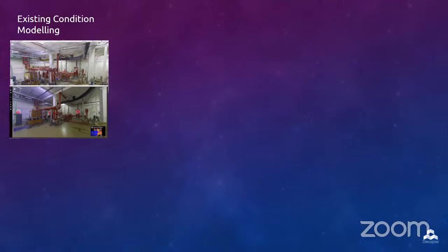Existing conditions modeling. Understanding the existing condition provides the project team with a framework for evaluating an existing facility and its system. When the design documents of the existing conditions are not available, the team may need to utilize other means of modeling these conditions. Techniques employed for documenting existing conditions may be laser scanners to point clouds, it might be photogrammetry, the exterior UAV photography, and manual field verifications. The majorly used one is the laser scanning, which saves countless hours of error-prone field measurements and often captures far more information than the traditional methods.